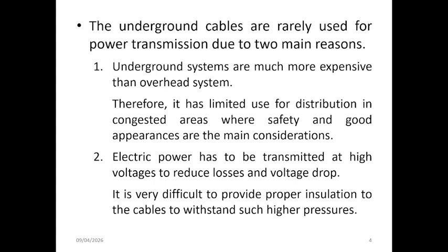Additionally, efficient power transmission requires high voltages to minimize losses and voltage drops. However, providing adequate insulation for underground cables to withstand such high voltages is technically challenging and expensive. Therefore, despite their advantages in specific environments, underground cables are generally less practical for large scale power transmission.